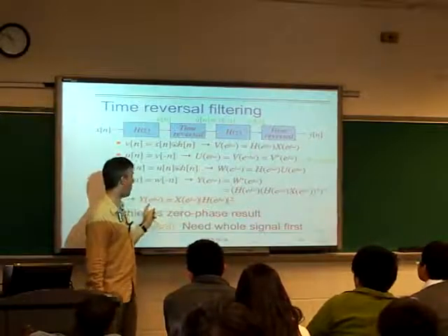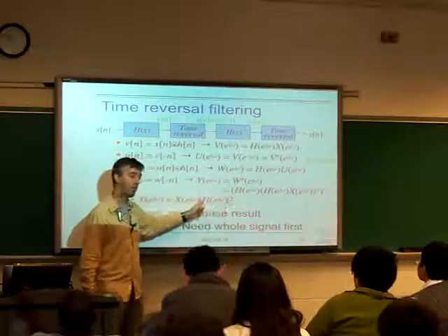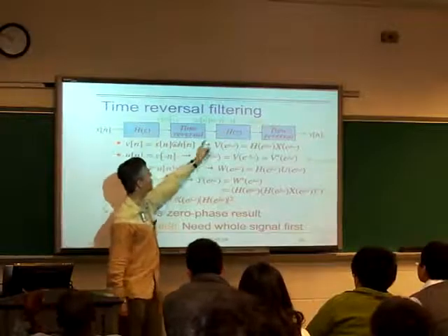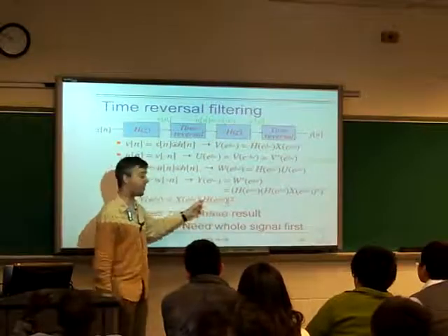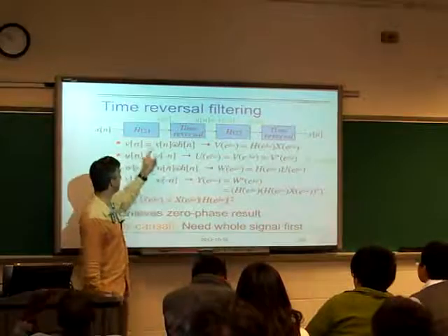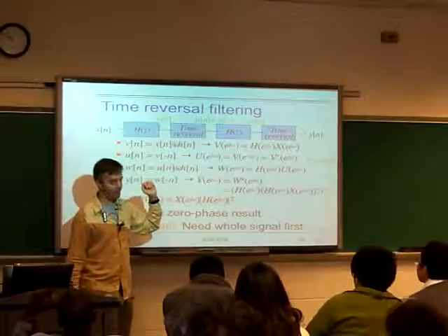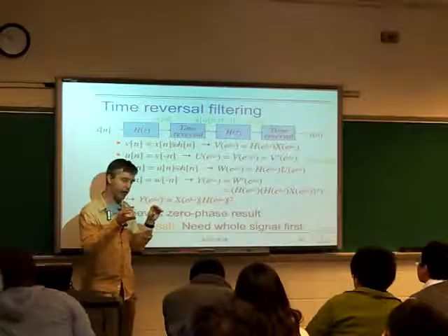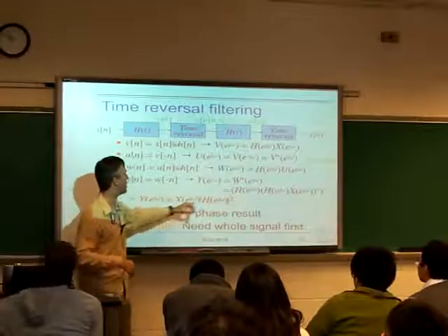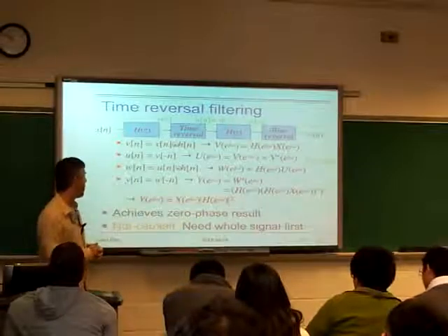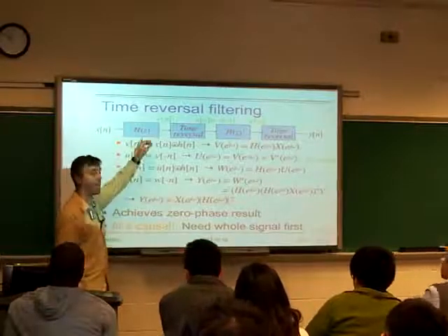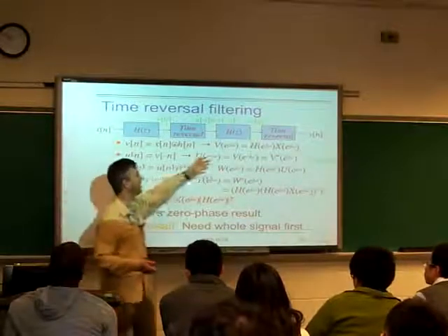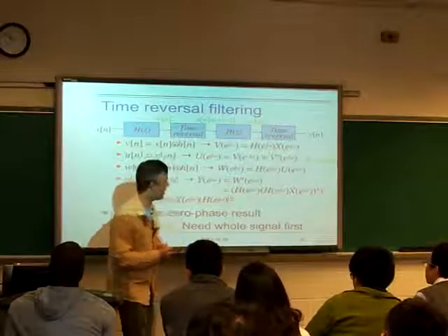This is the actual frequency response, but the frequency response is pure real, because the phase that was added in here was subtracted out here. But the overall gain is now the square of this individual filter, because if we think about each sinusoid, it goes through this filter twice. So its magnitude is modified by the gain of the filter twice, so we get the square. But this is nice. We can take an H of z with any kind of phase function, any kind of nonlinear weird phase function, and it automatically cancels itself out, nulls itself out.